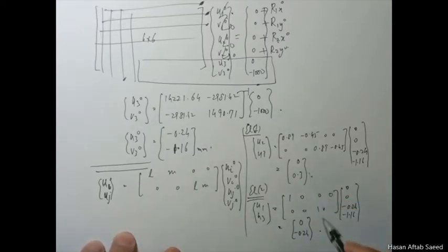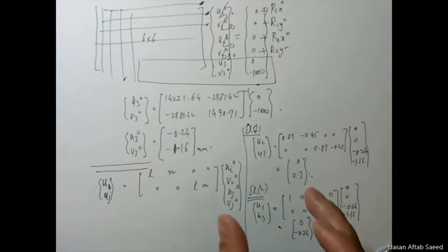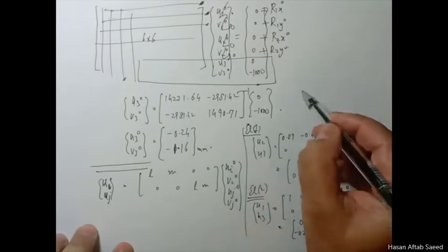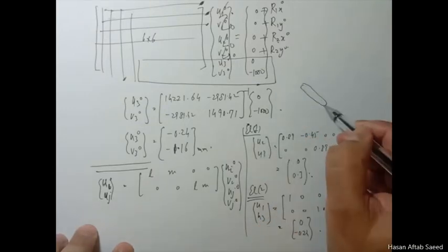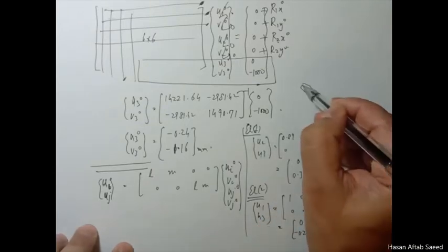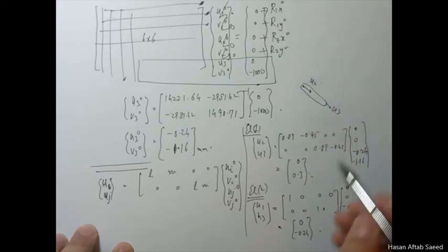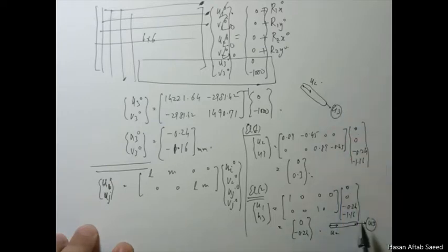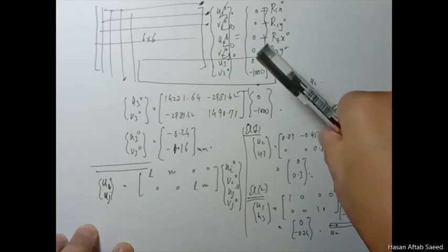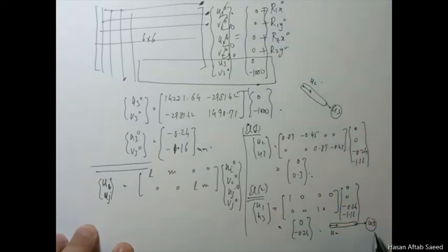These are the local values of displacements. Both u's we're talking about. For this element, u3, u2. For this element, u3. Please see that both are u3, but one is in this direction, one is in that direction. So these are local ones. So these are not u3 knots.